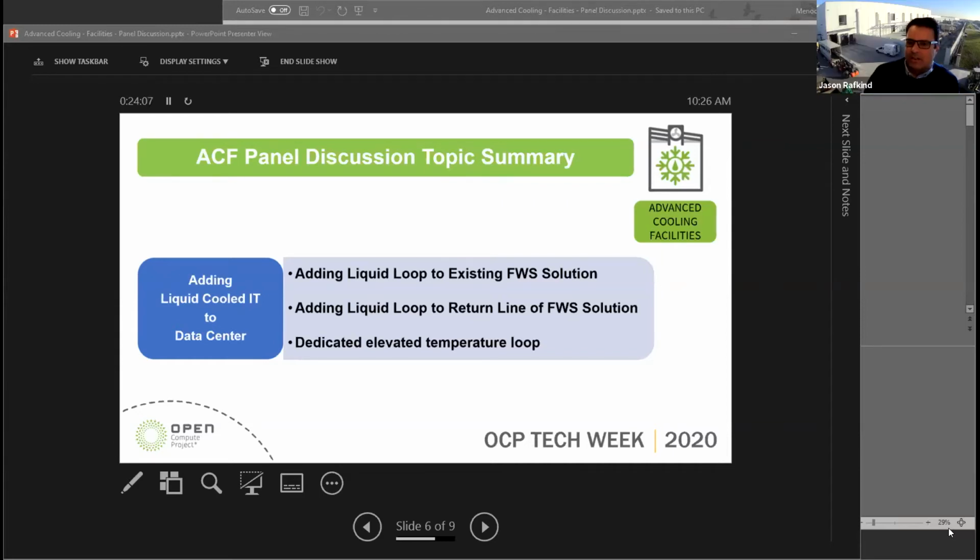Yeah, so our typical data hall is 18 to 20,000 square feet, and we have mechanical galleries along either side. And in those mechanical galleries, we have fan walls. So we are placing taps on either side of those galleries to be able to provide initially 1.2 megawatts of liquid cooling. And we're also sizing and operating our chilled water plant to support both air side, because we still need to meet the A1, A2, A3 ratings that our air customers need, and then also be able to provide a water liquid cooling solution. So we do have an elevated, but not an extremely elevated chilled water loop, more around 20C.